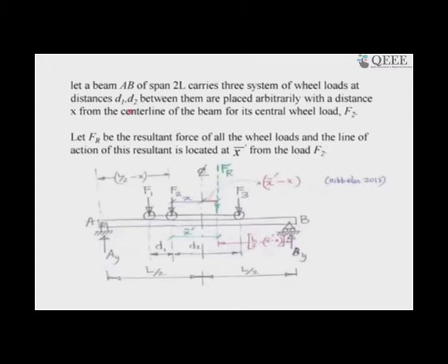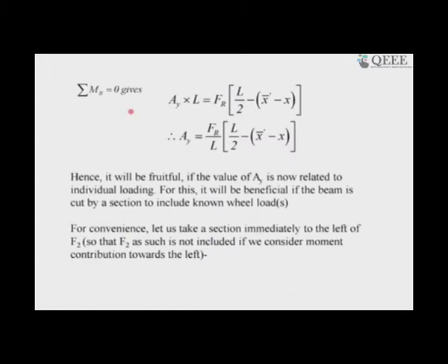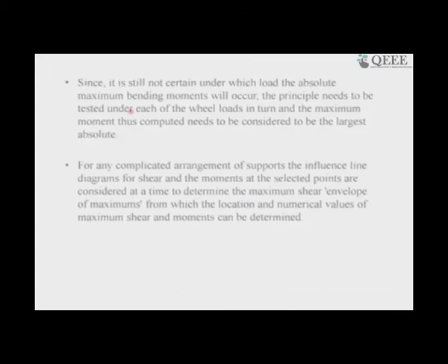Yes, we have also seen that one of the loads should be equidistant from the geometric center line from its resultant, the sum total of all the forces as a resultant. So, they should be equidistant, and that is the position which can make it maximum, but you need to investigate it for other loads if there are trains of loads. Yes please, next we have a problem solved. Yes, this is the conclusion.